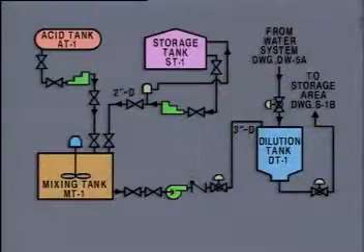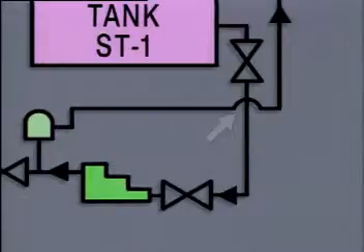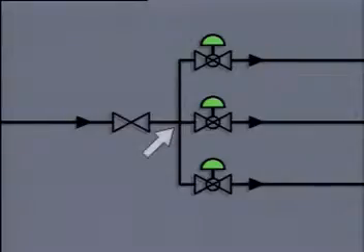The symbols for the valves and other equipment on a process flow diagram are connected by lines that represent the flows of materials in the system. Lines that cross with a hump or a break in one line represent material flows that are not connected. Lines that cross like this, without a hump or a break in one of the lines, represent flows that are connected. The same material flows in all 4 legs of the piping.